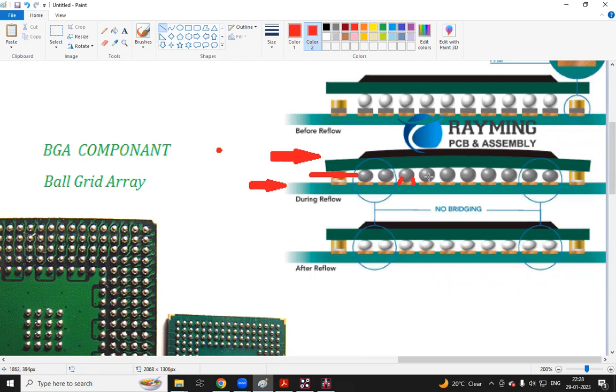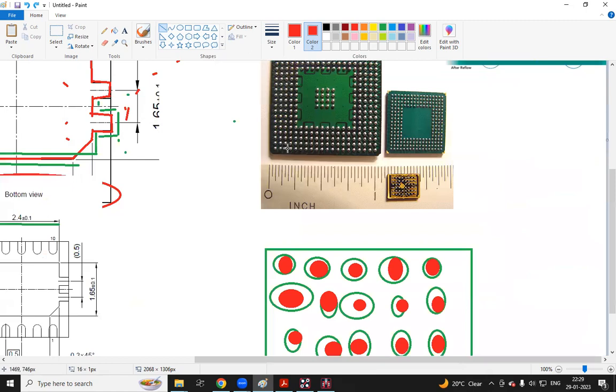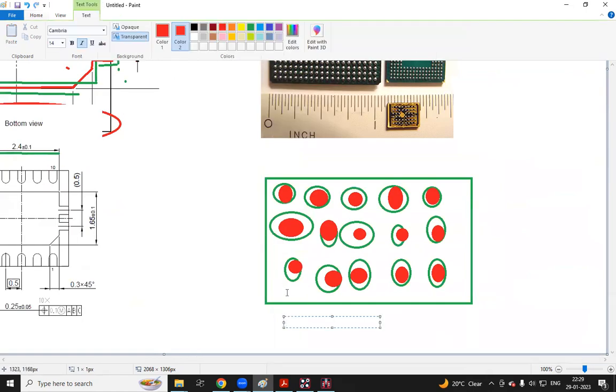So guys, if you see here, this area, if it comes flat, it can touch this pad and this pad also, right? Pankaj, getting my points? Sir, yes, there has to be enough spacing between. No, that's right, you will not get a space. Some things are there, I am just going to explain. If you see here, the pad is smaller than the ball size. So guys, there's a concept that comes here in BGA: collapse pad stacks.